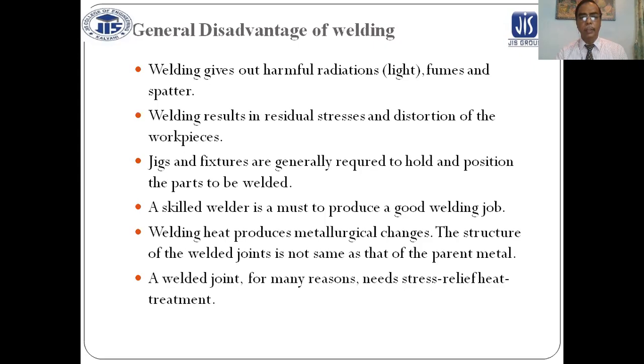A skilled welder is a must to produce a good welding job. Welding heat produces metallurgical changes. The structure of the weld joint is not the same as that of the parent metal. Welded joints, for many reasons, need stress relief heat treatment.